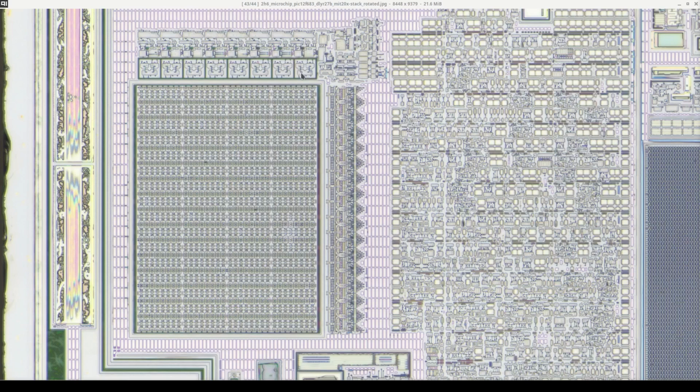And so this is going to contain the differential amplifiers for the bit lines, as well as a 4-to-1 mux. And then coming up out of the top here, we would expect to see the 8 data lines for reading and writing. And then down here is the word line circuitry, which will drive the word lines based on the row address that is input.